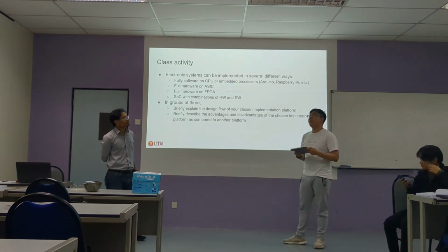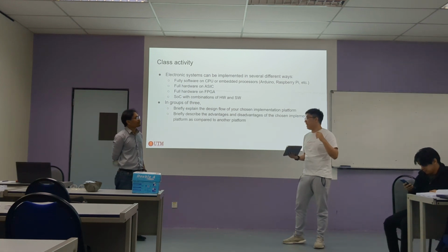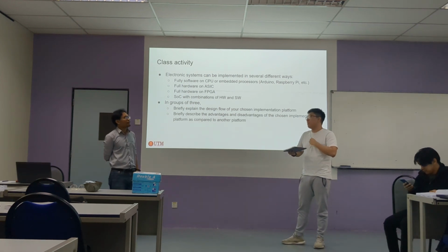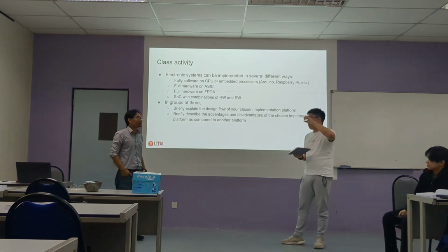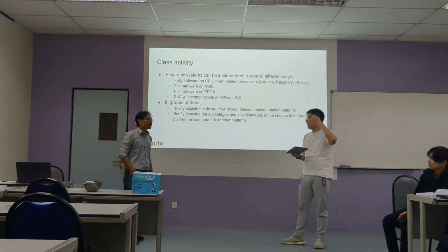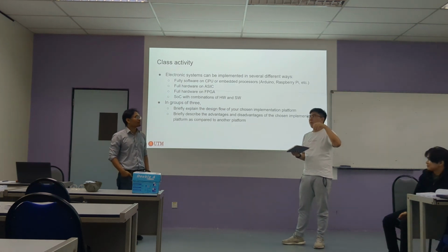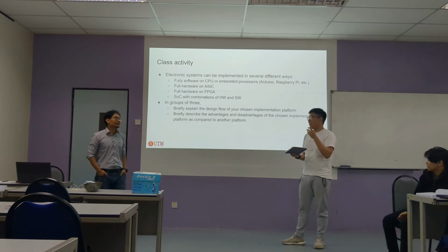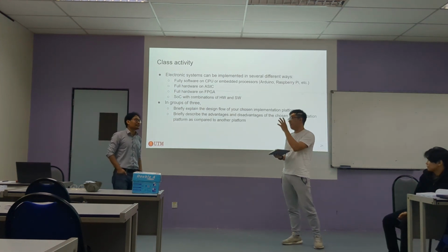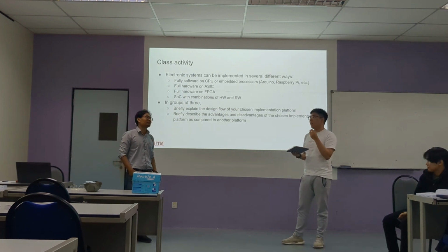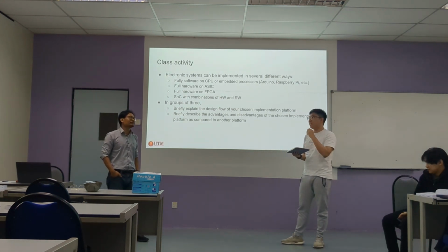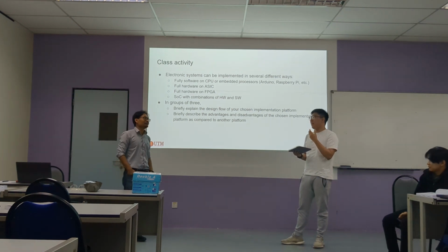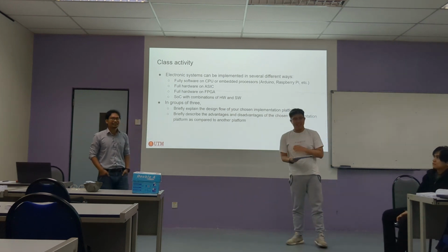And for FPGA, you do not need huge manpower. This is my personal opinion, it might be wrong, because for the entire ASIC you need a vast amount of verification for RTLs and a huge amount of manpower for the layout, and I think that's right. But for FPGA, there's no post layout methodology. So FPGA implementation is faster, requires less manpower, and is cheaper in terms of corporate execution and others. Yes. Good point.